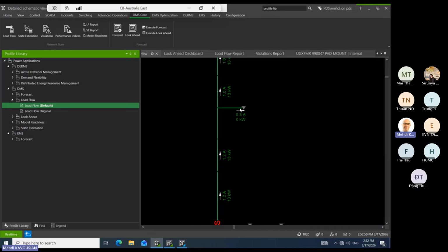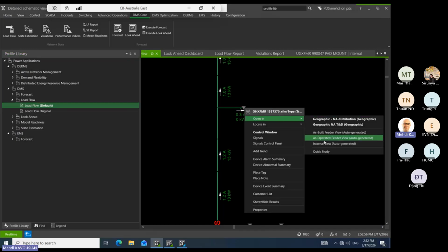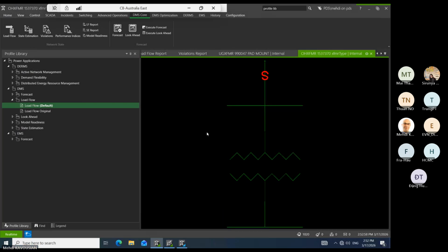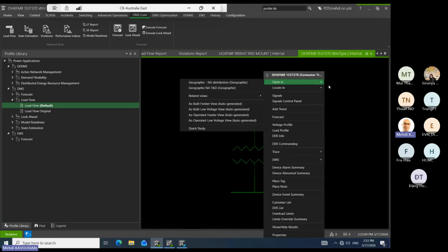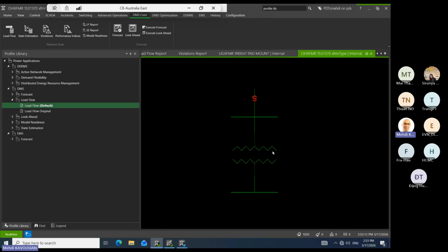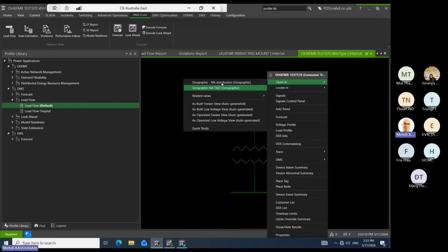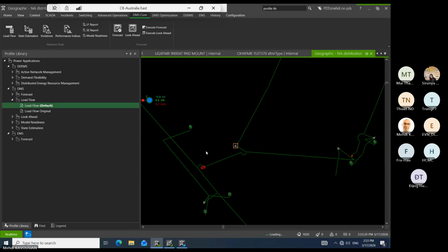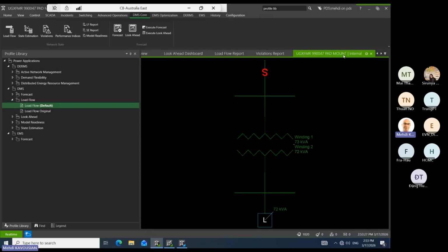in this case, you model MV, right? And then here on this transformer, I go to internal view. You would say the rest of this network, right? So you can see the rest of the network. Just sum up the load and make a load equivalent on the secondary side of this. I don't need to calculate every single element under that. I picked the wrong one, I guess, maybe I go to the previous one, it's better. Yeah, this one.